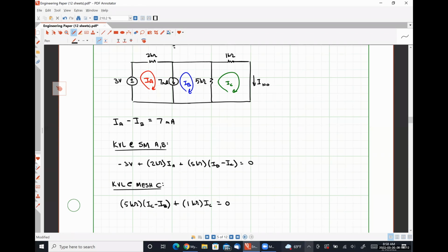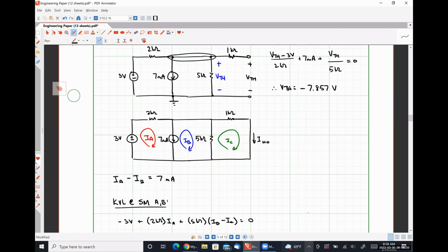Now we can solve this system, 3 equations, 3 unknowns. Actually, before we do this real quick, I just want to point something out. What if we had decided to use nodal analysis here like we did in the last bit? Our only unknown voltage would still be this guy, and our Norton current would simply be the voltage at that node divided by 1 kilo ohm. So we'd have a 1 equation, 1 unknown system and then one additional step to get our Norton current. So think about relationships like that before defaulting to nodal and mesh all the time.